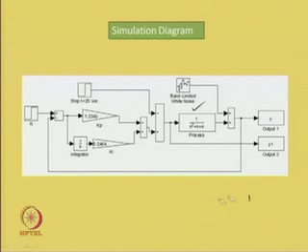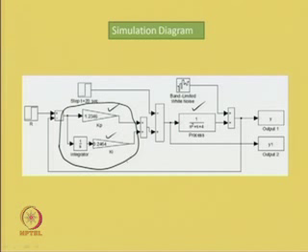Now, the PI controller is employed with Kp at 1.2346 and KI at 0.2464. So, this gives us the PI controller dynamics. We have the PI controller over here in the feed forward path for the process.